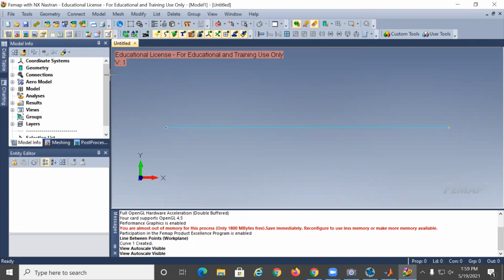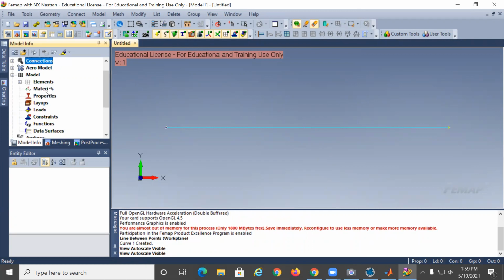So now we need to do the meshing, so basically to give some physical representation. The material doesn't matter because the shear and bending moment diagrams are not affected by the material. It's like the load: you can apply the load on the table and you will know the shear and bending moment diagram. How much it's going to deform depends on whether the table is made out of wood, steel, or another material, but it should not affect the shear and bending moment.